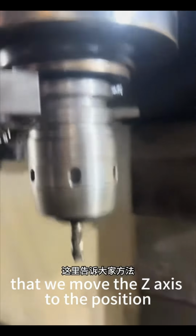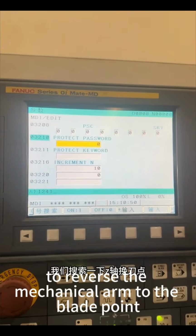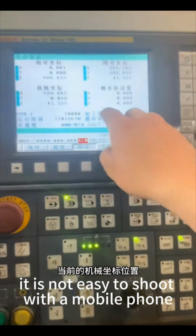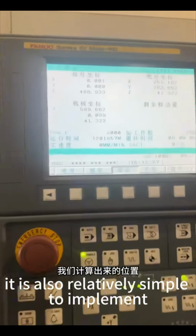We move the Z-axis to a position near the tool change point. Then we use the manipulator motor to turn the manipulator to the tool change position. Then we measure the distance between the manipulator and the tool in the Z direction. It is not easy to shoot with a mobile phone when measuring. Here I tell you the method. It is also relatively simple to implement.